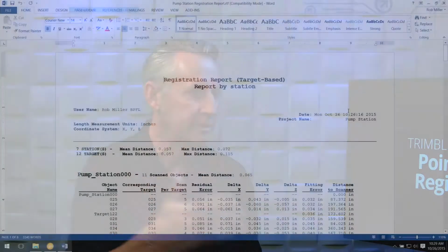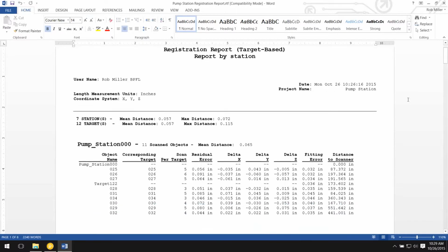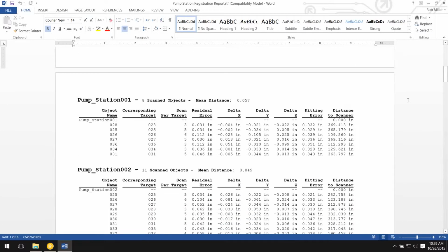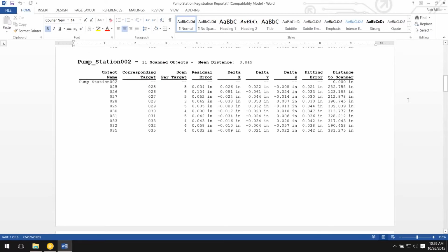Okay, so we have these different methods. Do we get different results, or are there any differences in the output of these? Yeah, I would say there are different methods, like any job site process. You have the options and flexibility with these different types of registration processes. But in the end, what you get is a quality control report out of each registration process. It gives you the option to evaluate that and decide that's the right one for me for this type of job.